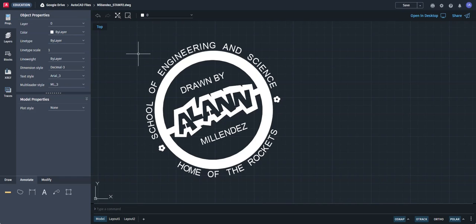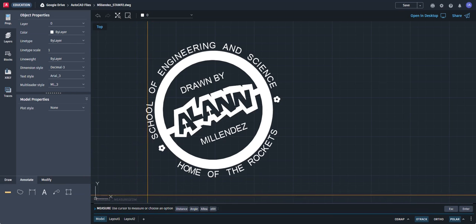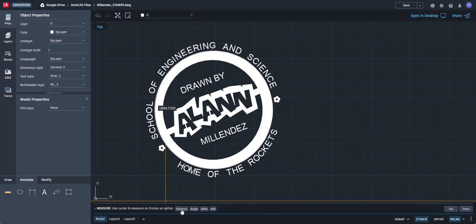Okay, what we're going to do next is make sure that this one fits a 2-inch by 2-inch square. So let's try to measure how wide and how tall this is. To measure, you go to Annotate, click on this ruler called Measure Tool, and then we're going to measure a distance. So we're going to click the Distance button here, and then select somewhere on the left, going straight to the right.